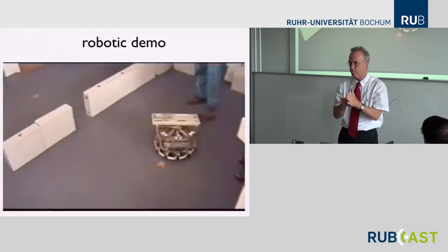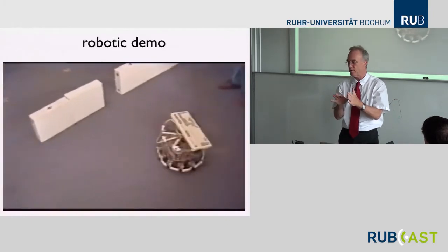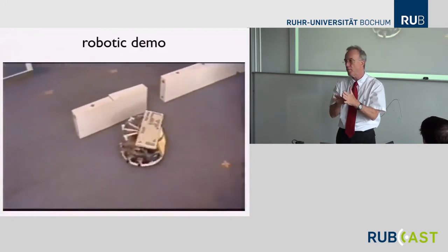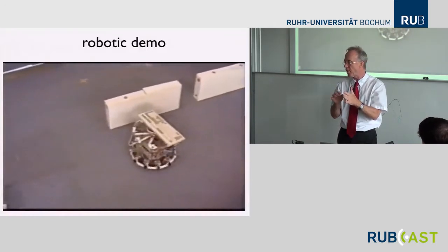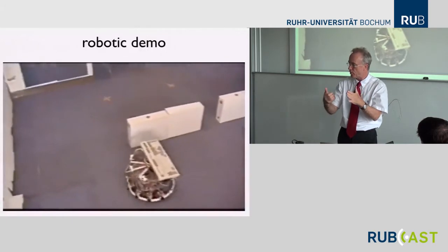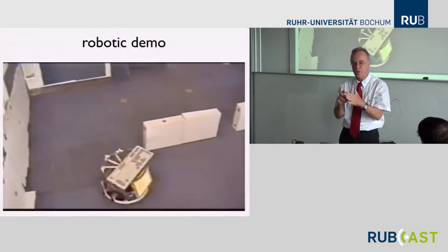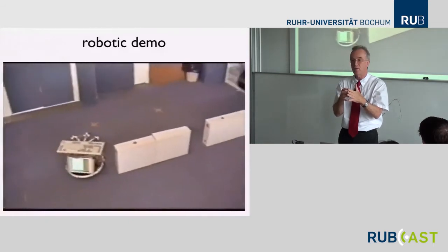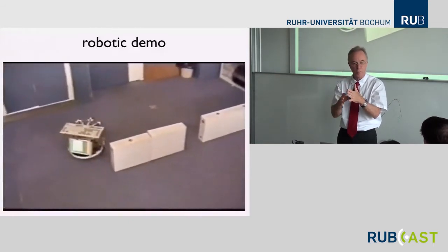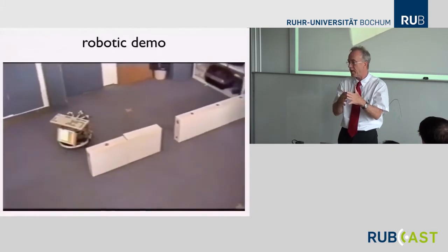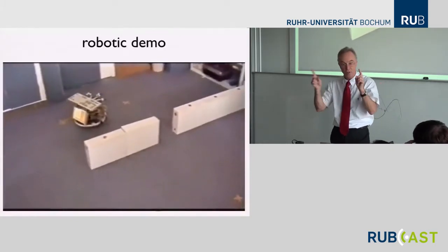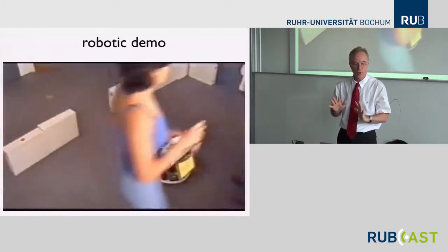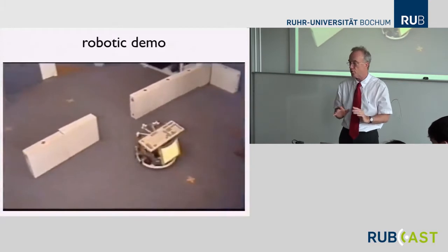Except for one case, right? When the two sensors are exactly the same distance. So generically, one sensor is closest to the collision point. So if you make sure that the repulsive strength becomes very strong when the distance becomes very small, then one sensor will dominate, the one where you're almost colliding. And then the dynamics will be determined by just one of those repulsive forcelets, and everything's fine. We're only interested in close to collision, right? Because that's when the constraint is important.